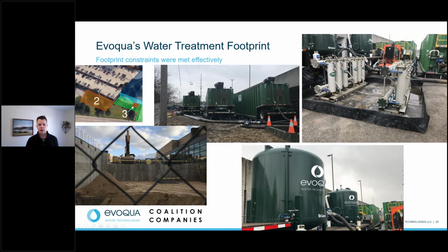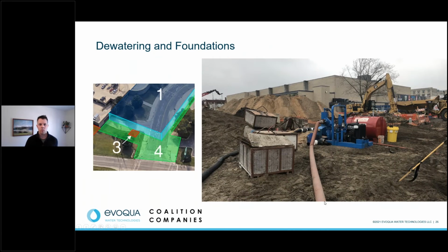So the blue here was our original building. This is where we set up our whole dewatering and treatment facility. Right here in red is where we had our dewatering pumps. And then the green is really the core area of where footing and dewatering had to happen. We did have a large U, where we buried this pipe in here that created a large U, and so it sucked up all the water across the site.